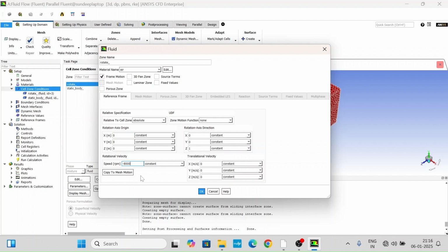negative because this propeller is a counterclockwise propeller. So in order to get thrust in the negative Z direction, we have to rotate it in the counterclockwise direction. So with this minus, make sure the RPM rotation is in the counterclockwise direction. So that's it.